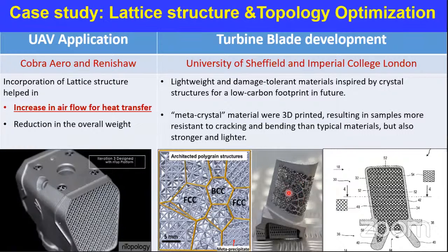You have a lot of lattice structure, and they themselves behave like cooling channels. And number two, if the design is not permitting this, people are trying to have through cooling holes in the blade profile itself, which can take care of different types of cooling techniques like impingement, transpiration, such cooling methodology.